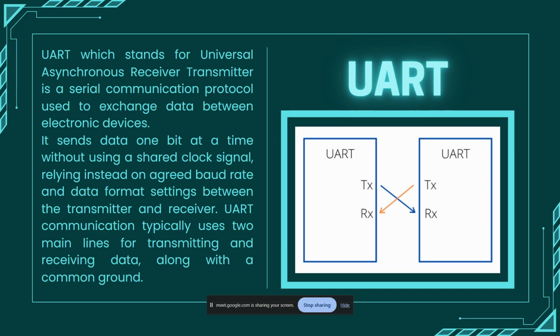But UART, I2C, and SPI together lay the foundation to all the cheap protocols. Our comp teams have high budgets and they rely on speed, so those guys use CAN. But first of all, UART. UART stands for Universal Asynchronous Receiver Transmitter. Now, universal, you can scrap that word. Asynchronous just means that there is no clock signal. Receiver transmitter, we have a receiver and a transmitter. So the name means no clock, receiver and transmitter.